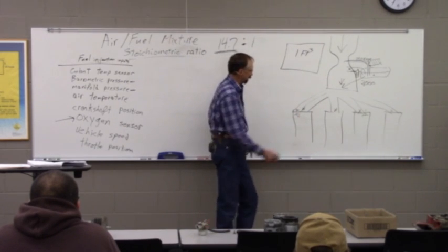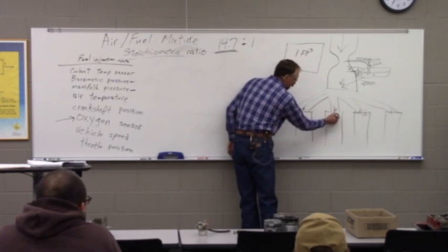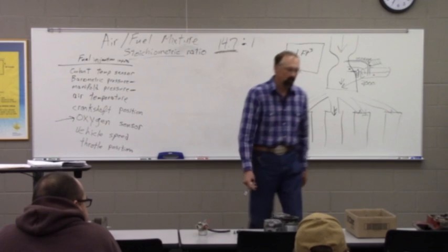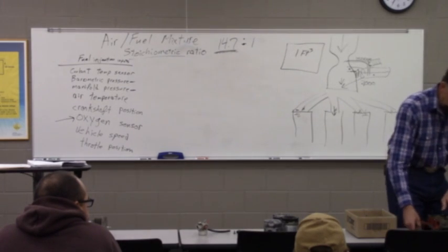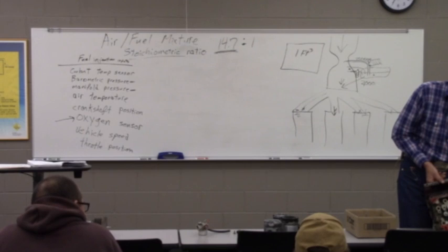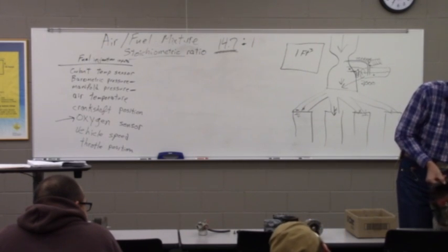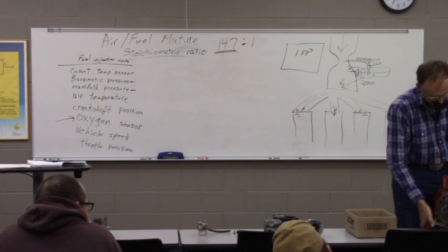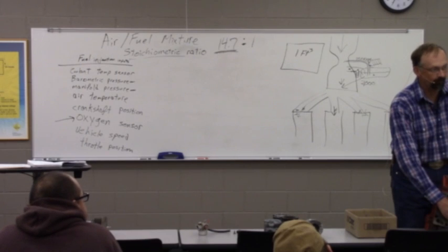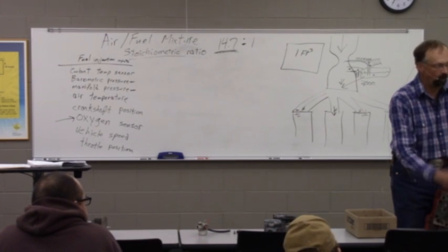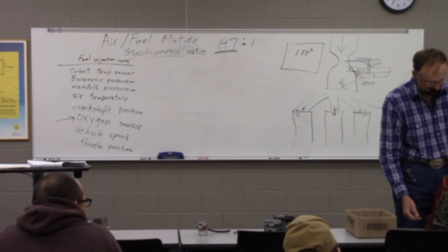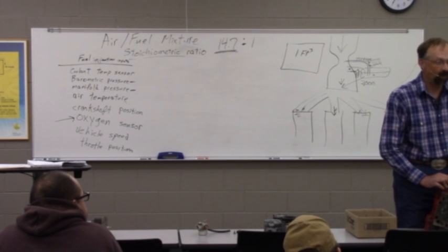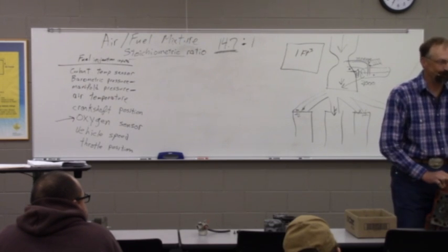So typically in the diesel, the tip of the injector is actually right in the cylinder. On this cylinder head, you can see this is the bore where the injector goes, and the tip of that injector comes through this hole right into the cylinder. So we're actually spraying the fuel directly into the cylinder when we want combustion in that cylinder. So the diesel engines have always been sequential multi-port fuel injection.